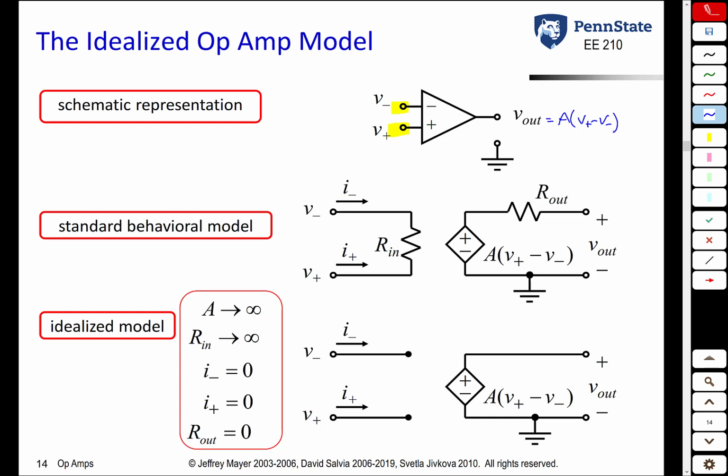When we talked about the Opamp, we then saw that using the Opamp in open loop mode is something that we typically do not do. Instead, we connect external resistors, capacitors, and other components to the Opamp and use it in what's called closed loop mode. We then saw that to try to solve Opamp circuits, you had to use a model for the Opamp.